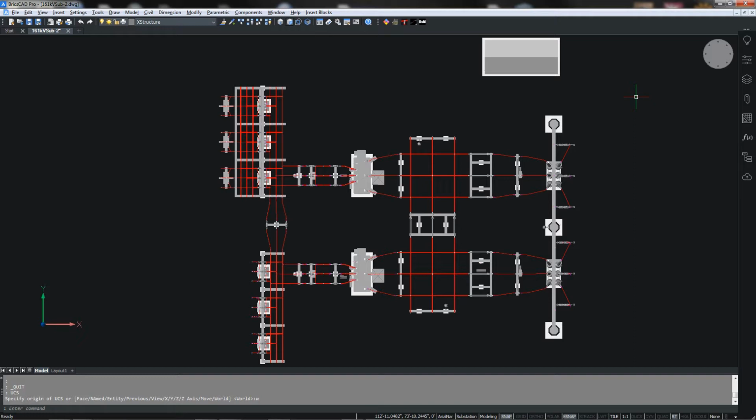And in this video I will cover substation lightning protection design. Before starting, however, let's review the substation configuration. This is the same substation we've used in our previous videos, and we're coming into a 2-bay substation with 161 kV and stepped it down here to 12 kV where we've got 3 outgoing underground bays on this bank and 3 outgoing overhead bays on this bank.